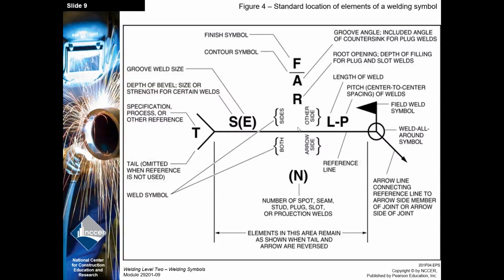These parentheses here indicate where the weld symbol goes. No ing there, just the weld symbol. So a triangle, a V, a U. These are the different grooves. Maybe just two parallel lines indicating a square groove. But that's where your weld symbol goes.